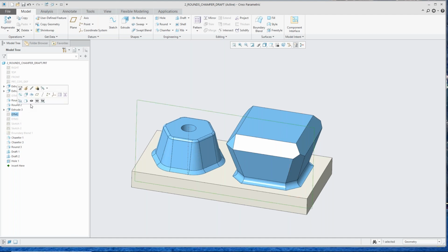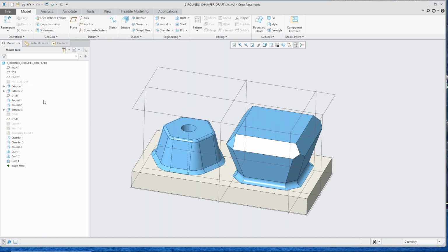And then if we wanted to hide this guy, I could say, hide him. Another thing I could do is say, show only this datum plane. And so he's displayed right over here. We can kind of see it on the right side. One of the things I noticed, there isn't a hide all or a show all. So you have to do it kind of in two menu clicks, show everything except this thing and then click that thing. But anyway, new capabilities.